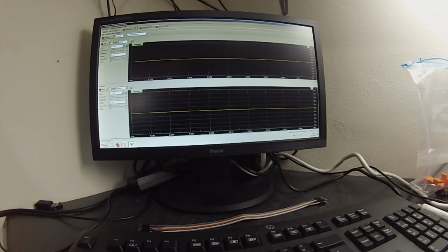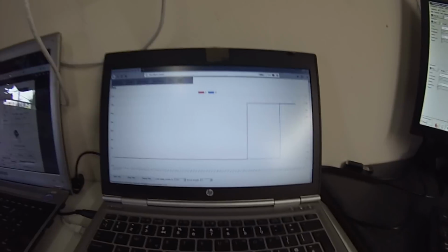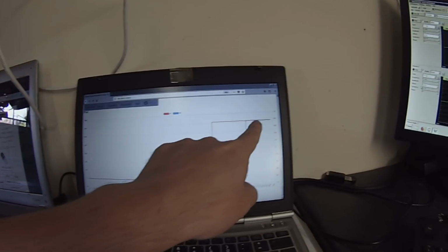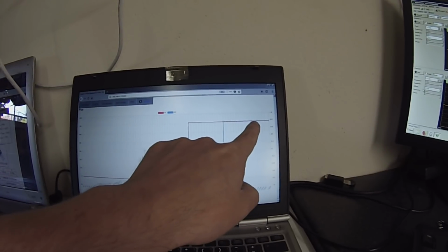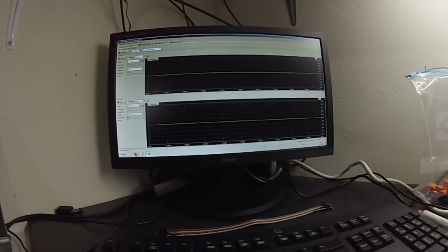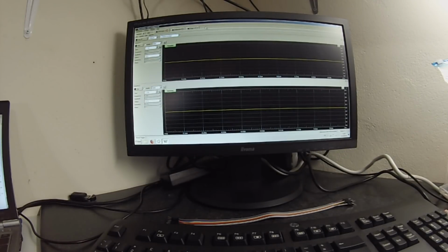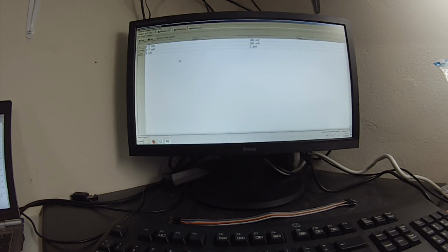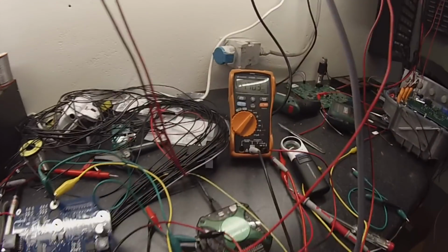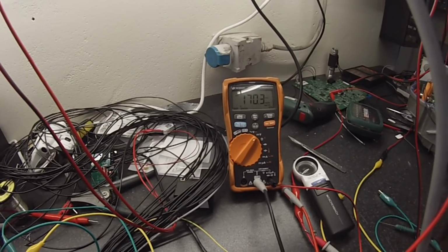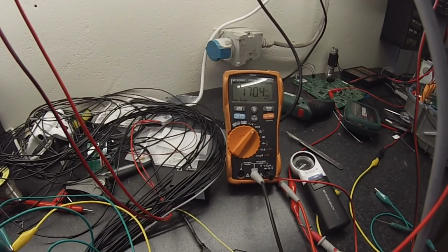Okay, so what we'll now see is that we are reading a current of just over 1200 amps on our graph, and our inverter is still working. Because if we look again at our voltmeter output from the signal conditioning circuit, you will see that we now have 177 and 182 millivolts coming out, and that is above the 170 millivolt lower trip point.